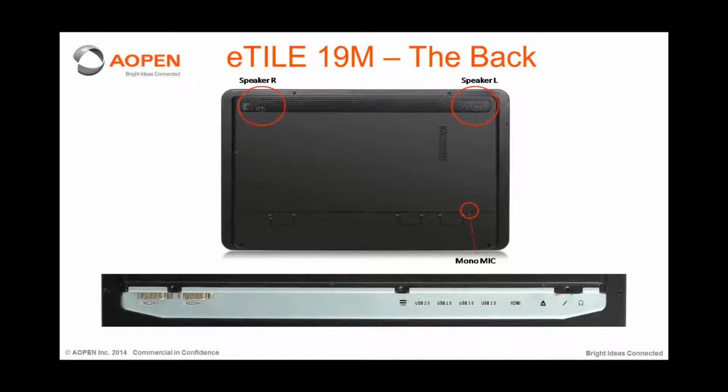The connectors going from left to right: 2 times RS-232 ports, power plugs supporting 12 up to 19.5 volts, so it's not 12 or 19, but 12 to 19.5 volts. The included adapter provides 120 watts at 19.5 volts.